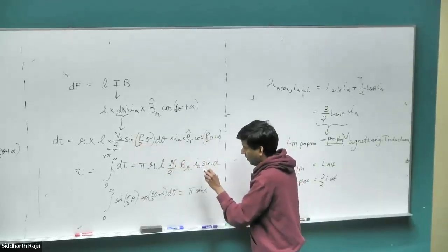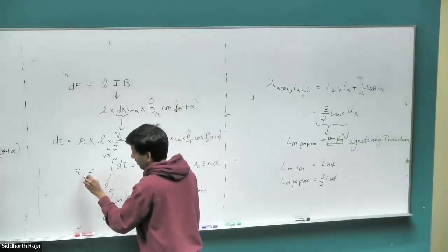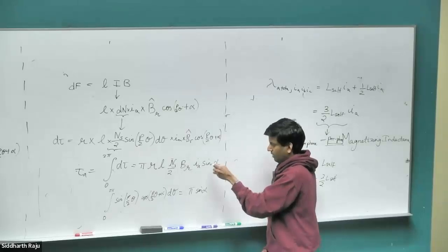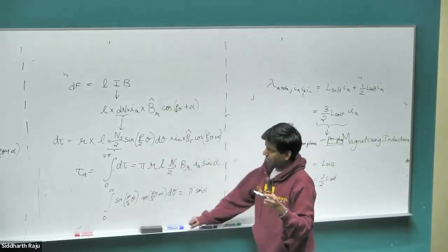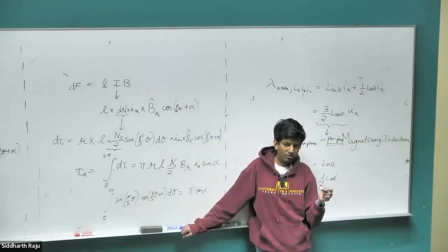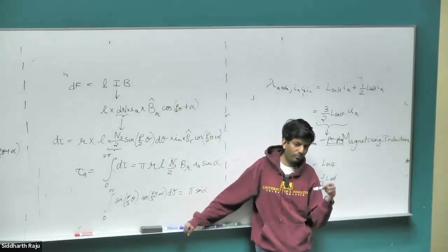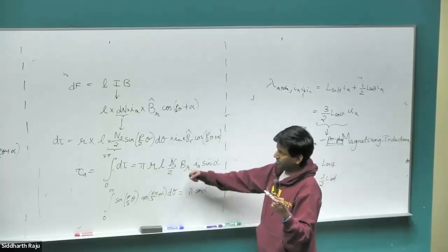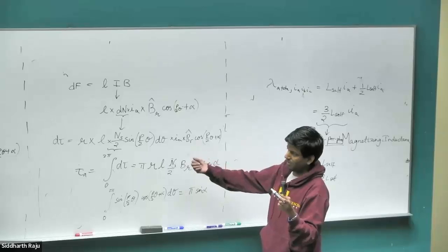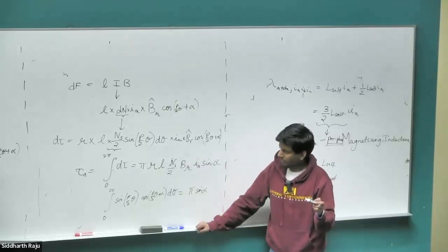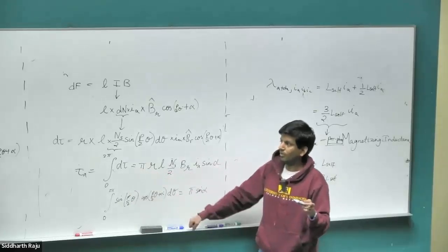So this is the torque experienced by the stator due to the magnet, due to the current in the A phase winding. Right? But we have latched down the stator. The stator is not going to rotate. So we know that if the stator is experiencing the force, the rotor experiences an equal and opposite force from Newton's law. Since the stator is latched down, the rotor is going to experience the force and start to rotate. Right? The torque experienced is going to be exactly the same value.